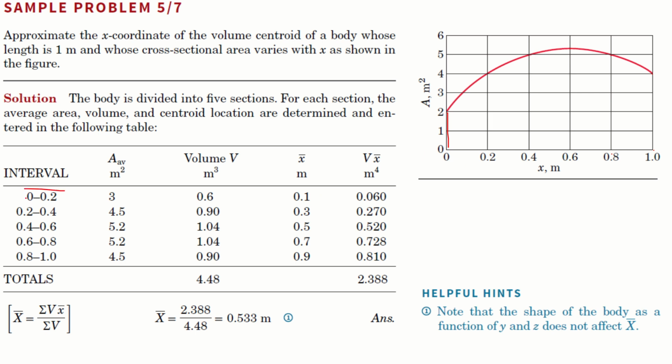So for each thickness we are calculating the average area and this volume formation. From this volume formation we can find the x prime of that particular cross-sectional area, and we can find the volume times that particular sliced area's centroid. We take this information for the total number of slices, and we can find the position of the center of the volume with respect to the x-axis as given right here. This information is from right here, and we can find the position of x prime.